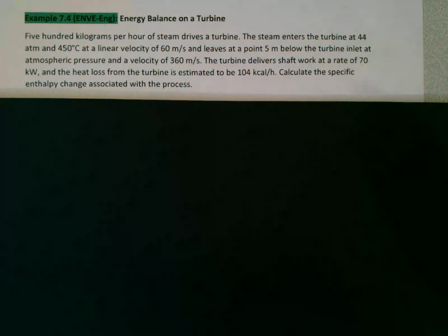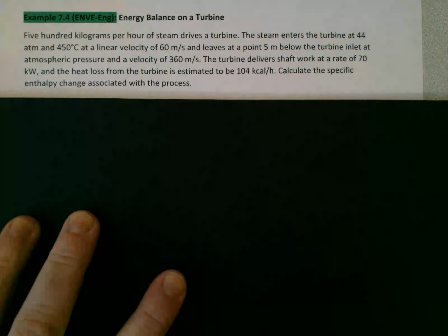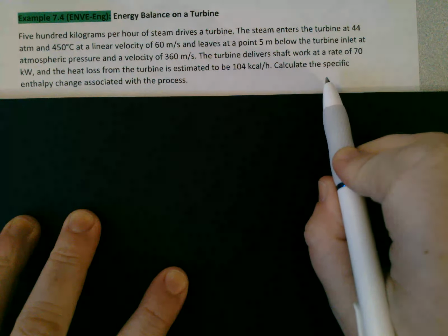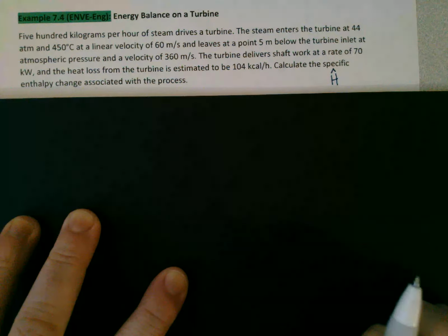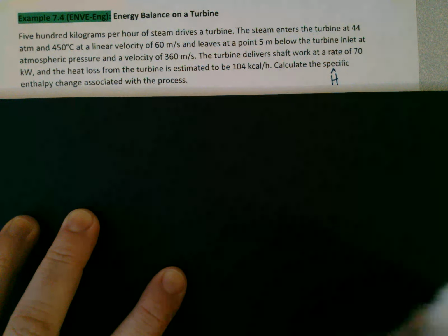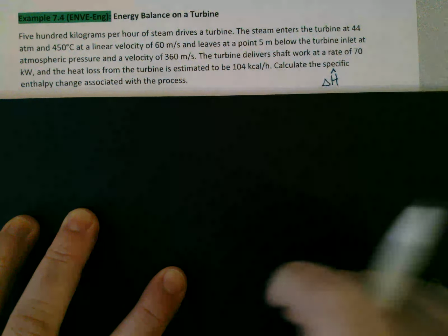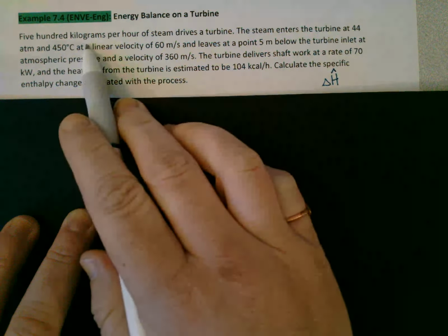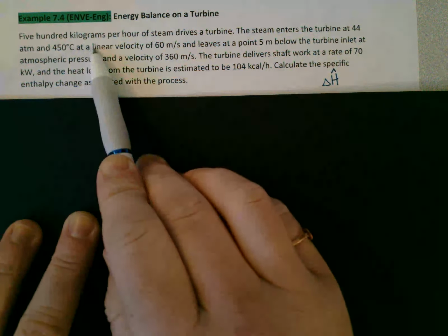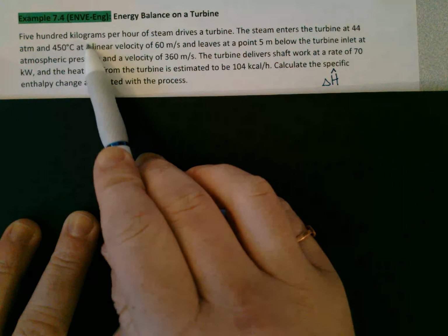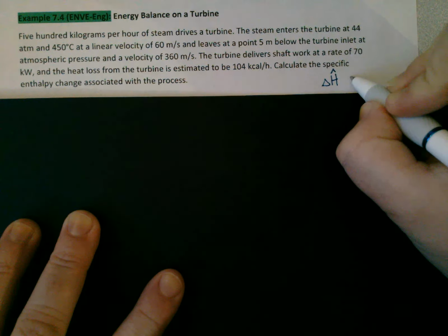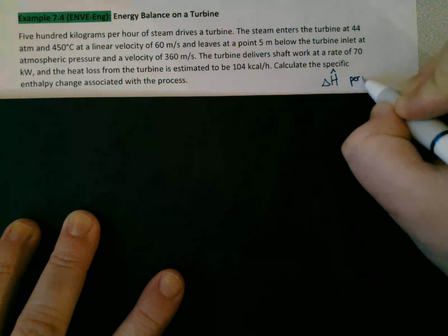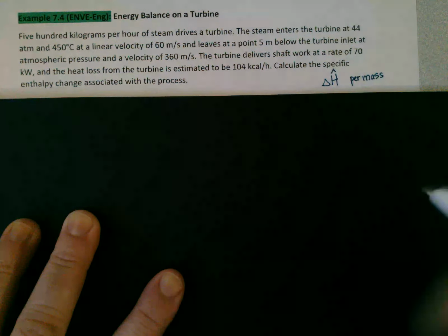Okay, so there's a lot of information going on here. We're putting all of our concepts together. So at the end of the day, one of the things that we want to be aware of is what we're solving for. We're looking for specific enthalpy in this case. So we're looking for H hat or a delta H hat. And if we look at the problem, we want to know whether that's a molar specific enthalpy or a mass specific enthalpy. If we look at what we have in the system, we have things in terms of kilograms. So this is per mass.